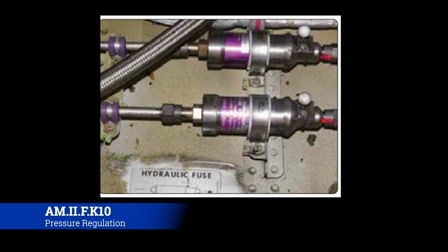The reason is, what they don't want to have happen is some sort of leak or burst, or a bird strike takes out a hydraulic actuator or what have you, and you just eject all of the hydraulic fluid into the atmosphere and leave the plane basically not able to be flown, because the hydraulic system is basically broken down.